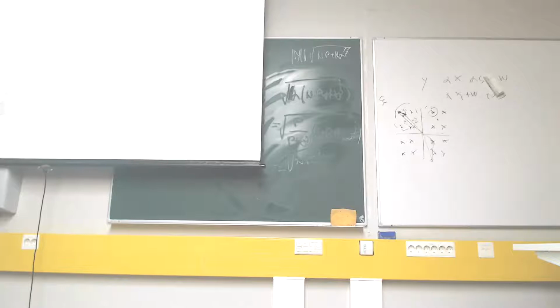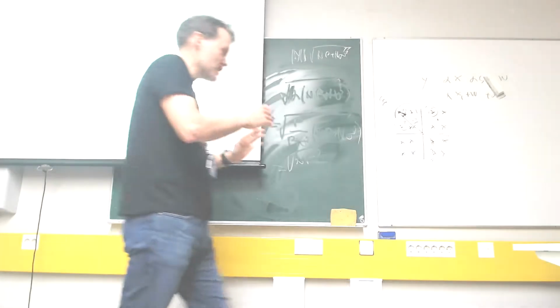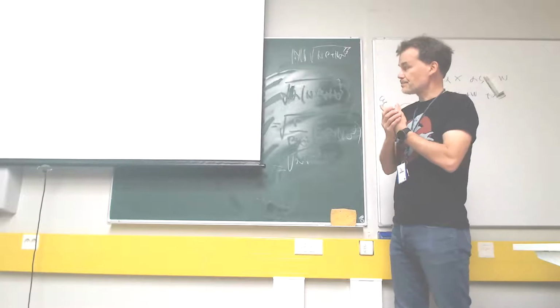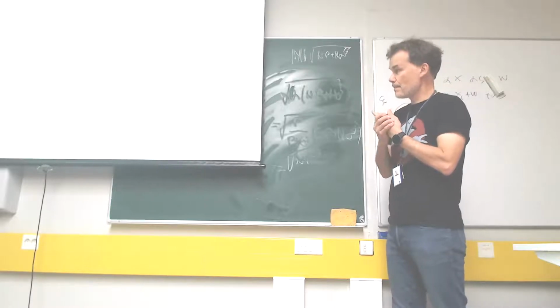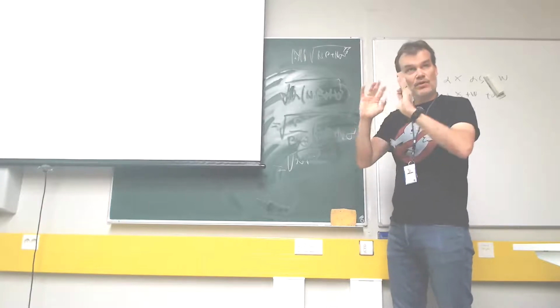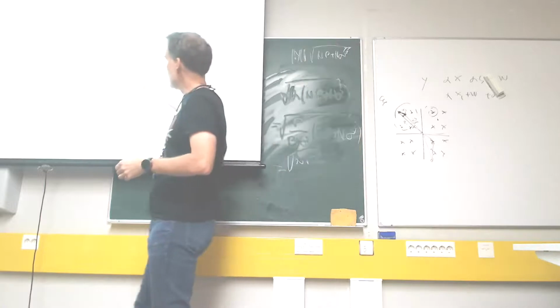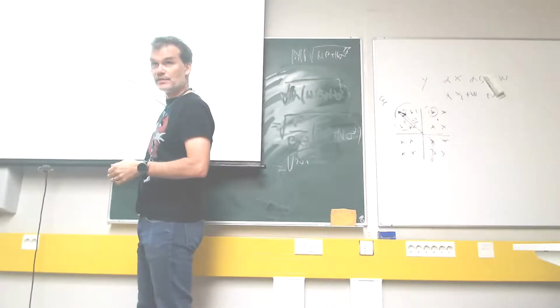Scaling by the MMSE is information lossless, right? So for the single user case, this scaling doesn't matter. But for this interference case, when we want to replicate these alphabets or constellations, we want to replicate these X spheres, right?